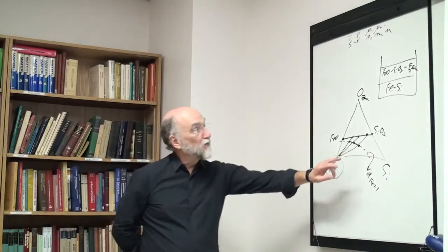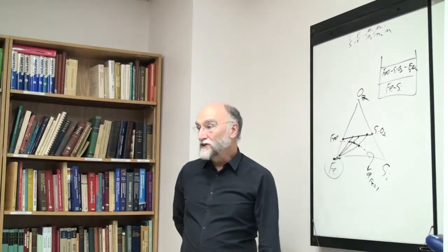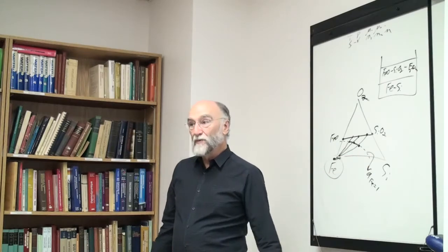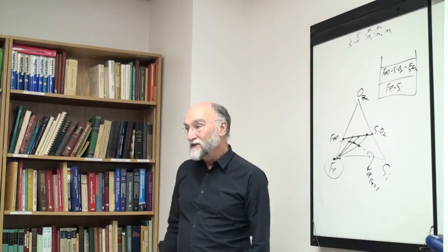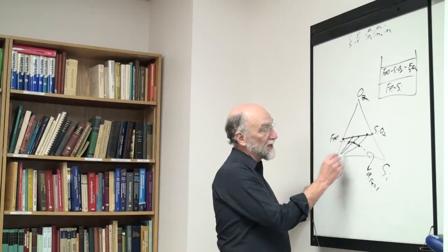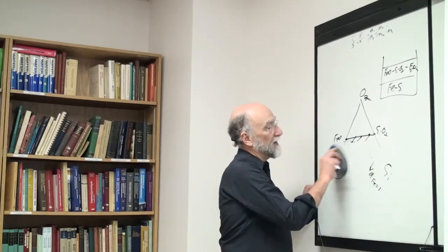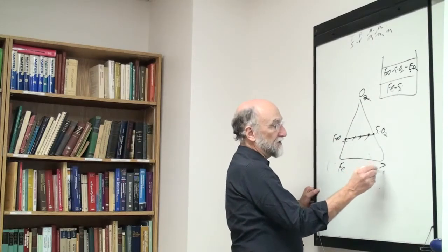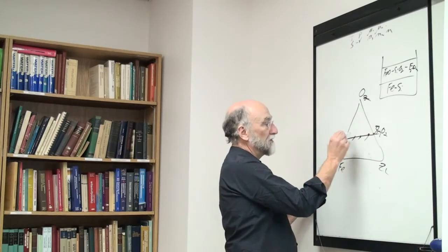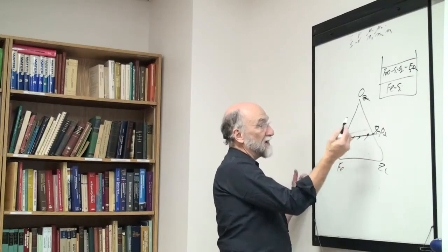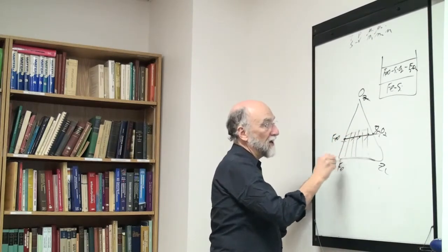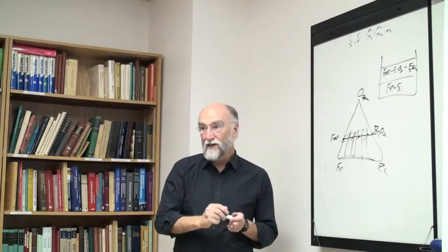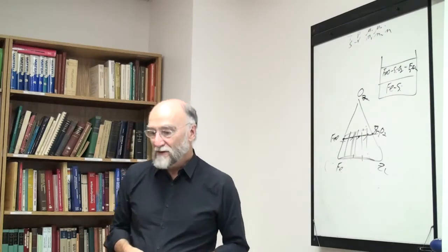the case. The activity of iron is 1, but if I had, say, the iron zinc oxygen system, then this phase could actually contain more zinc than iron in many cases. Okay, so I can't really do this in actual fact. What I really have then, if I had iron zinc, okay, if this was iron zinc and this was zinc oxide or something, then the slag phase up here would be in equilibrium with an alloy along here, so I'd have tie lines like this, and it's not. Okay, so that's your problem.